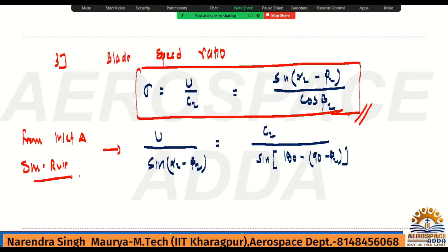All right, so these are the performance parameters. Now the last topic is the free vortex design for the turbine. There we have points for the free vortex design, and formulas: when you have the root radius and the mean radius, you can calculate the tip radius. Similarly, if at least the mean radius is known, then with the help of the diameter and the free vortex design calculation you can get the other radius.